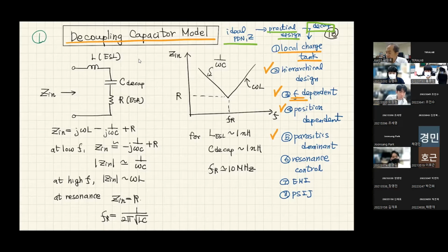When we are putting many decoupling capacitors, there will be some resonances between decoupling capacitors, and between interconnection inductance and interconnection capacitances. Naturally, it will happen. So we have to somehow control it, to avoid overlap of the frequencies of your current spectrum with these resonance frequencies.